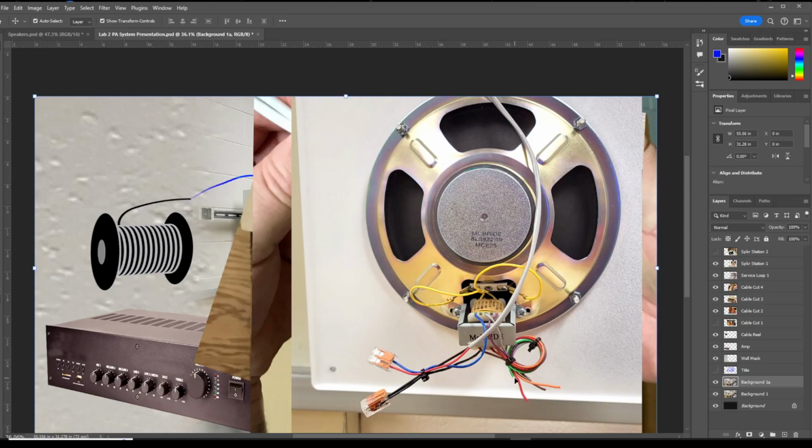All the other wires, we just need to not connect them, but it's a really, really good idea, and it's a must thing. They need to be secured in a way that the endings are not left stripped and free to touch anything. So they just don't rattle against any of the surfaces.